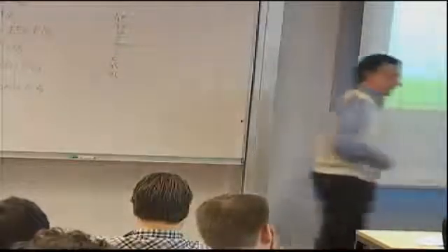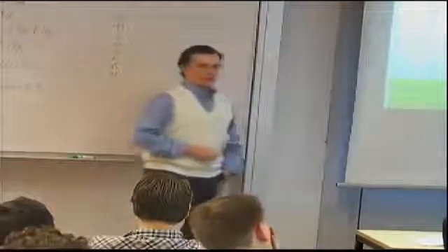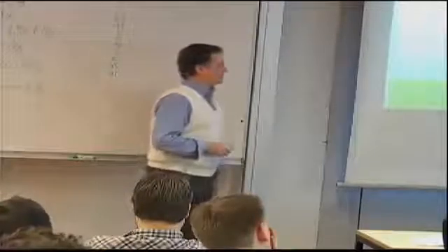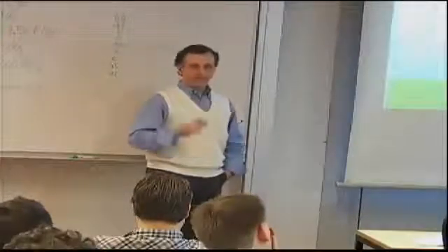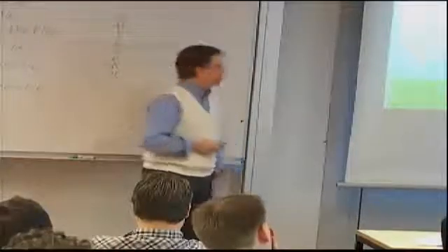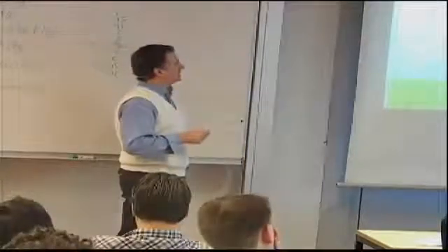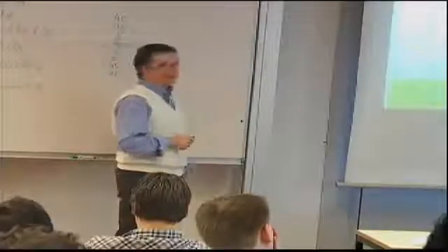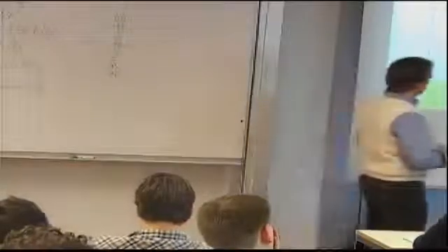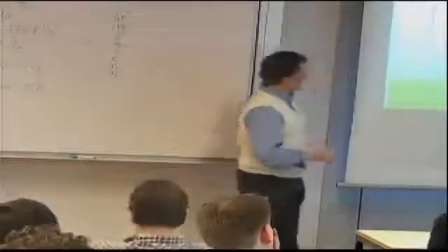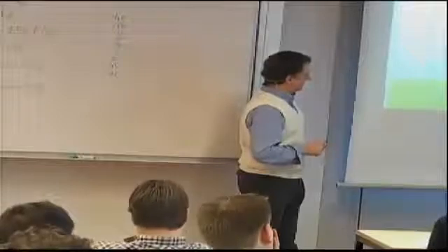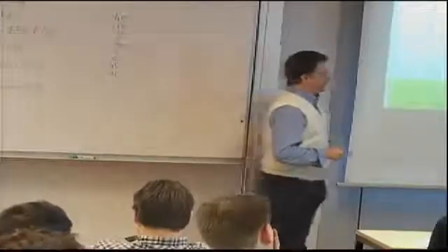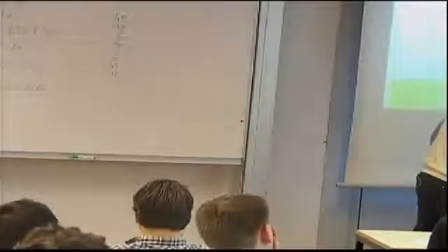And there's a variation of those equations if you're trying to do a buckling analysis, you have to include some kind of first order effects. And briefly mentioned here is how you would do the force equilibrium in the Z direction. And the book has complete derivation, in much more detail. Basically, if you look at this equation at the bottom here, I have the D matrix with the force derivatives of W, and those are the same. Whoops, wrong way.